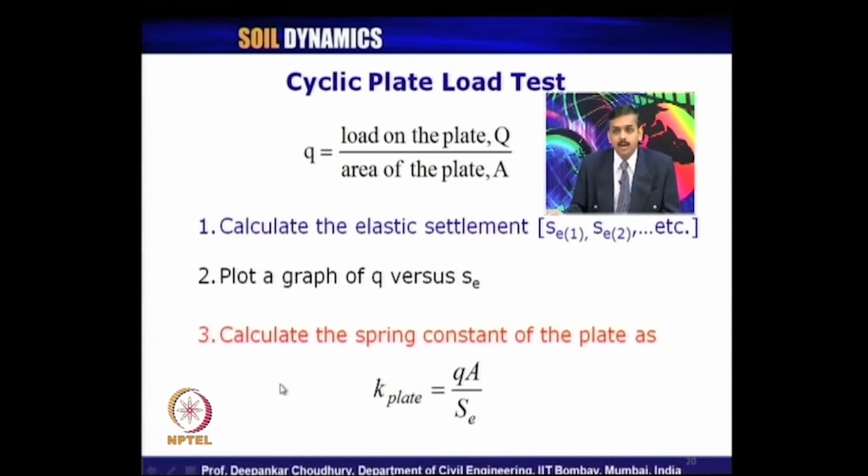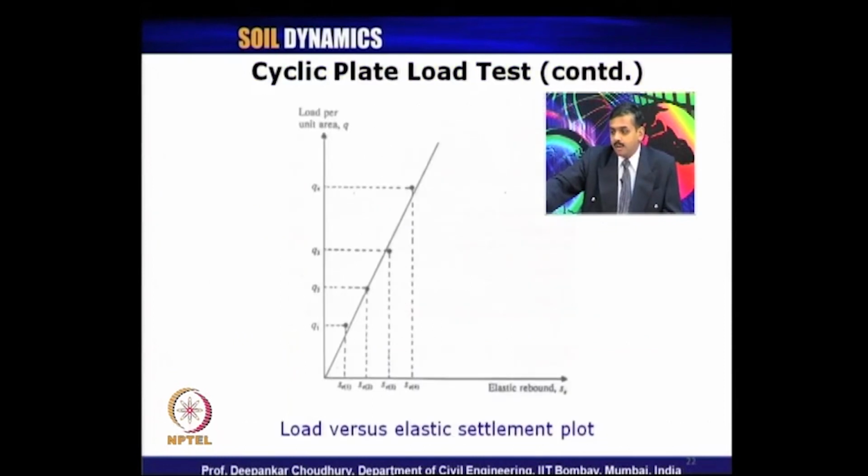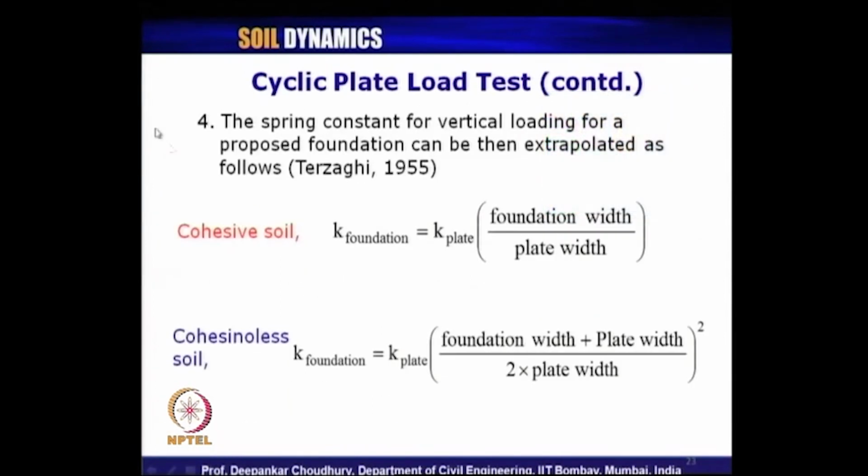Now, we need to convert this stiffness of the plate to the actual footing or actual foundation which we are going to use. The same thing that we have done for the static load test, here also for the cyclic load test we need to apply. So, let us see how we can compute the stiffness of our footing, because for any design we should know the stiffness of our footing material.